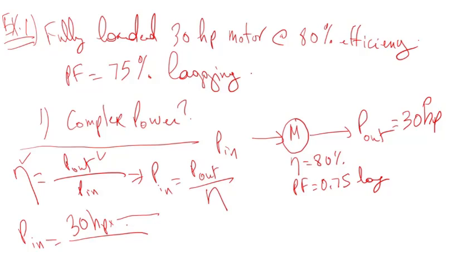I know 1 horsepower is equal to 745.7 watts. I would recommend watching videos I made on how to convert from horsepower to watts. Efficiency is 0.80, so horsepower will cancel out. So if you carry out this calculation, you get Pin is equal to 27.96 kilowatt.